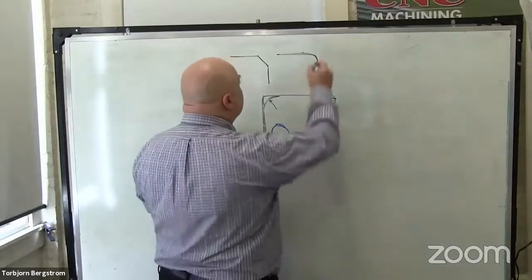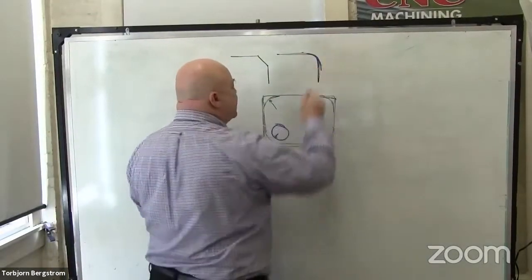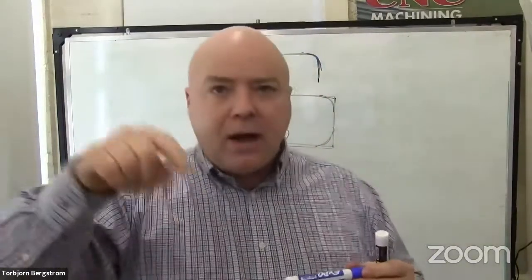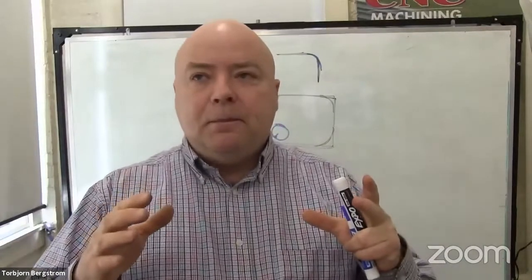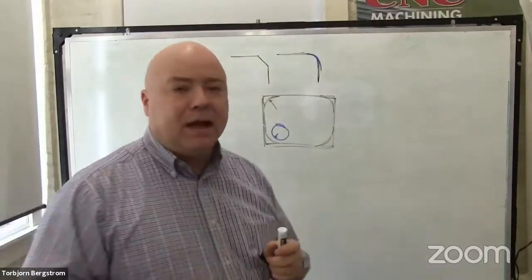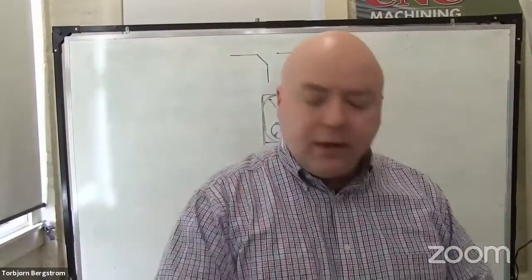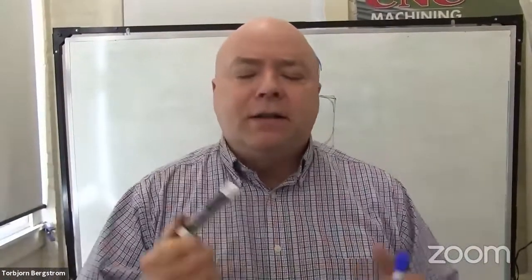In the CAD software, there's a button that says just fillet all the adjoining surfaces. That's really cool because you can press that button and it puts those fillets all over all the corners. It'll do it for chamfers too. It doesn't have to be just a fillet. And then there's an option where you can blend them together, and it looks really cool on the part, right? To make some surfaces, you do have to blend those different radiuses together.